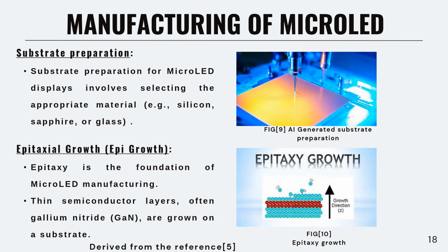I already said that we are using gallium nitride as the semiconductor material. Then we have to think about why we use gallium nitride. There are mainly three reasons. First is the wide band gap, which means that it handles high electric voltages and operates at high temperature without breaking down. Second is high electron mobility, allowing for efficient electron transport within the semiconductor.